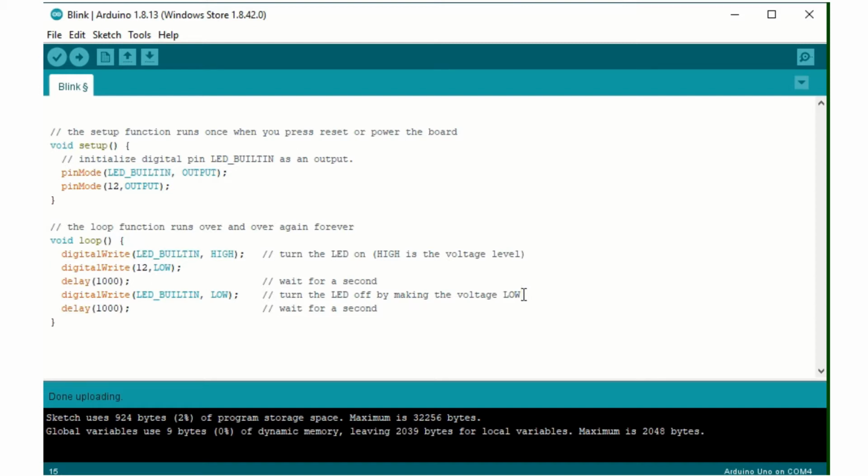So we'll go digitalWrite, pin 12, LOW, oops, I didn't put a comma in there. Low, close the brackets, semicolon. What's happening after that? Then, in this case, the white LED is going to go off for 1,000 milliseconds, or a second. What we've done here is turn the blue one off, but we've also turned the white one off again. The white one doesn't want to go low, it's already been low. It wants to go high. So I need to put HIGH in there. Okay, got it.